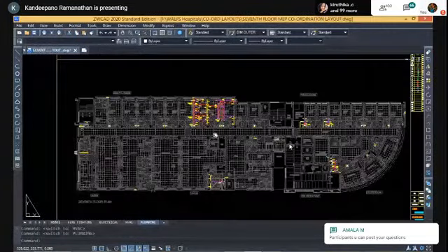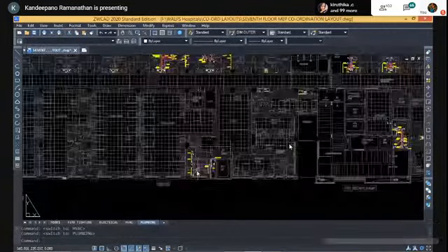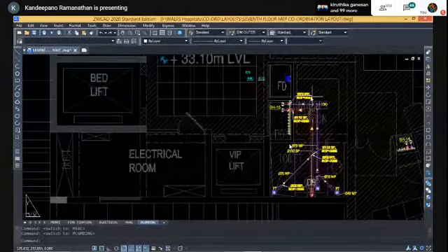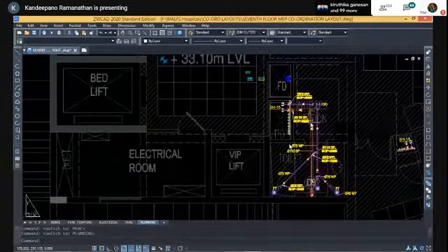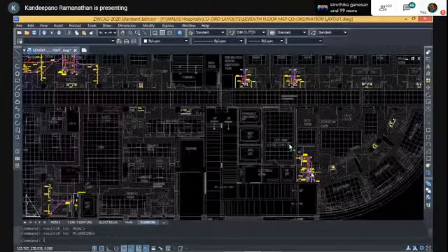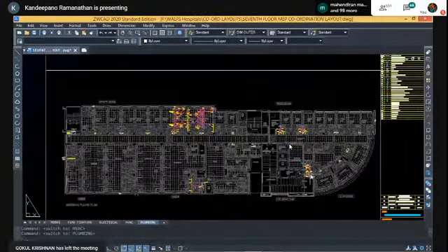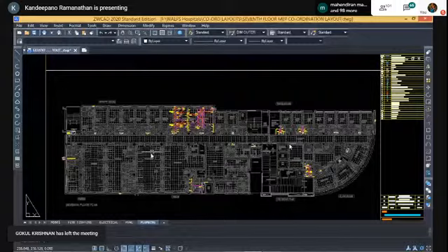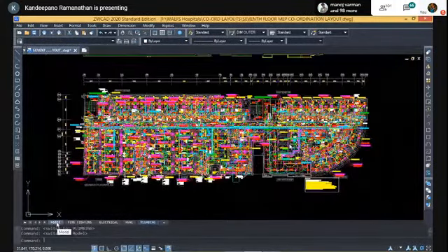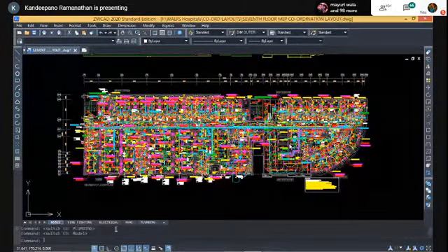And this is one major toilet, one more major toilet over here. Oh, there is piping below the slab for the toilets and going into a shaft and going down. Now this is a plumbing layout. Once these layouts are done individually, people do a coordinated drawing, everything in one layer, one sheet.